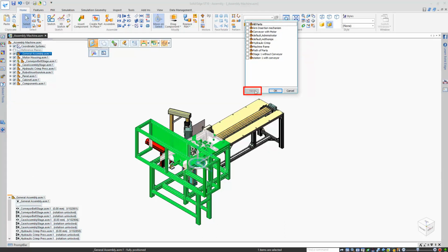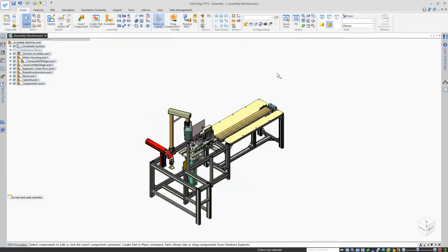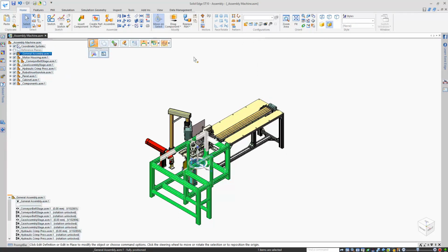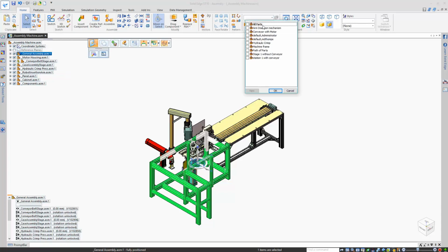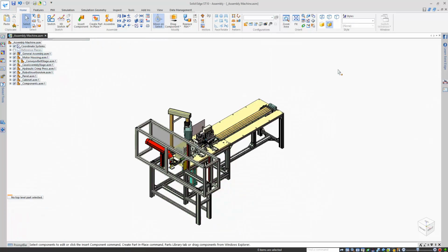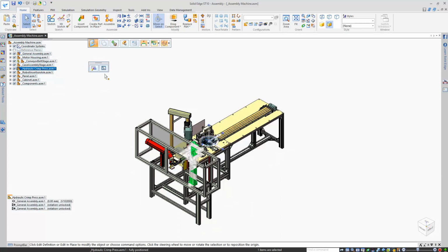This is the configuration list for the subassembly that I have selected, and I could apply this to the existing top-level configs if needed. However, it's read-only, and that might be a problem. So let's try editing the subassembly configs. Edit in place should do the trick, right? Well, not really, but I'll explain exactly why while we see for ourselves what happens.